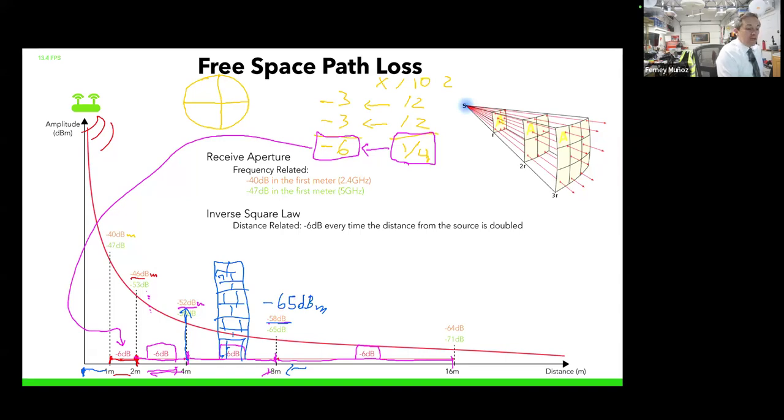But now, with that door or wall or window or rack or whatever it is, I'm just drawing a wall as an example, but whatever obstacle that is, at 8 meters now you measure neg 65. You should have neg 58. So what is the attenuation index, roughly, give or take, of that obstacle that is now in between? Well, 7 dB. That's going to be roughly 7 dB.